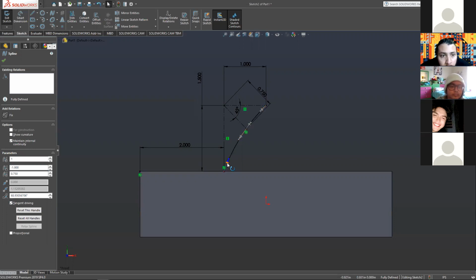We're gonna select this little arrow kind of coming out here, and it gives us all the properties, the parameters over here on the left, and it'll tell us the angle that's coming out of that point. We want to select tangent driving, make sure that's selected if it's not, and let's set that angle to 0, and bam, the curve changed.